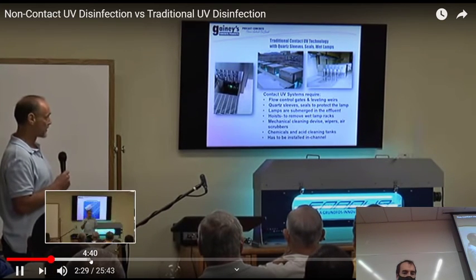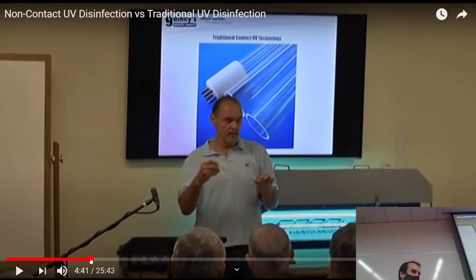So you just mentioned that they require control of the flow, and that's because they're using the water itself to cool the lamps. So you have to maintain the right level of water. If you had some sort of change in the flow rate for whatever reason, you don't want the lamps to get too hot and burn out. So that's one of the challenges there. You don't have that same challenge with the other system.